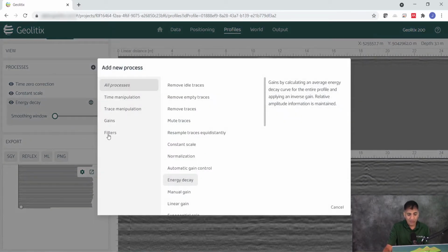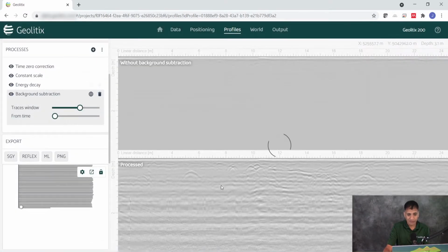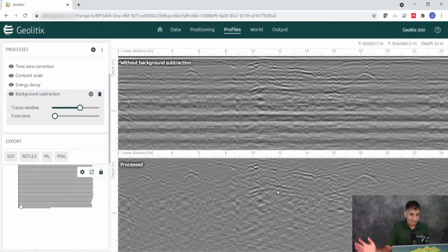A complicated way would be a 2D FFT, but a much more straightforward way is just a background subtraction. Done. Great. So now we have our hyperbola. I can see my targets quite easily. Let's go ahead and figure out what kind of velocities we're dealing with here.